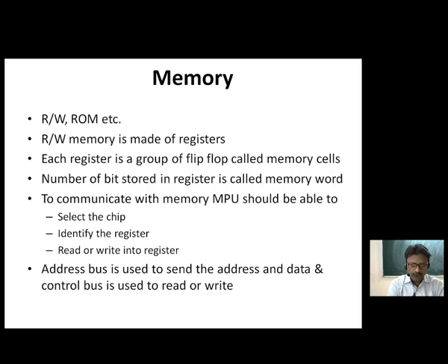For doing all these we require a certain address, because individual registers present in the individual chip are designated with a particular address. So we are in need of the address bus to carry the address. We are in need of generating the control signal for reading or writing purpose, which is generated by the microprocessor.